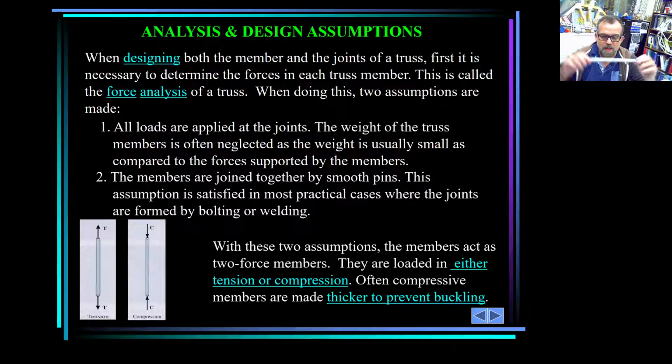Now, usually, and you know that it's not the same thing in tension as in compression. When the members are in compression, usually these members are thicker because when I'm pressuring these, the member is going to buckle in different modes, but it can buckle. And if the member buckles, it's going to become unstable. So usually the members in compression are thicker in the trusses just to prevent that buckling. Or we have auxiliary members that we're going to explain later as zero force members.